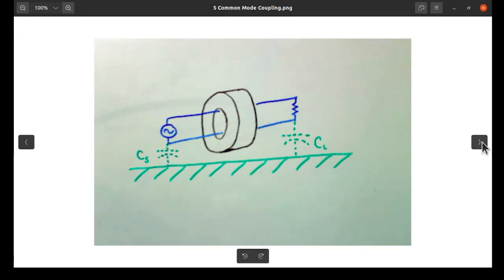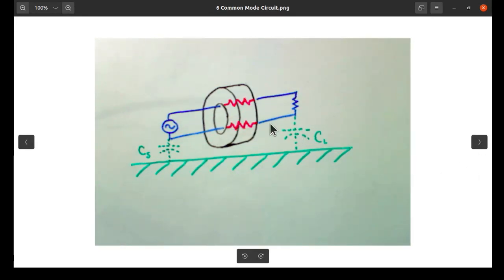we'll just move to the next slide. In this regard, we have now resistance, the resistive characteristic of the ferrite is introduced into both leads as resistive elements that create a voltage divider, R and R to this source, which is to say something is getting lost, power that's flowing in this direction is getting lost in regards to this load. Now, this is a tricky image in that this coupling and this coupling introduce a current path.